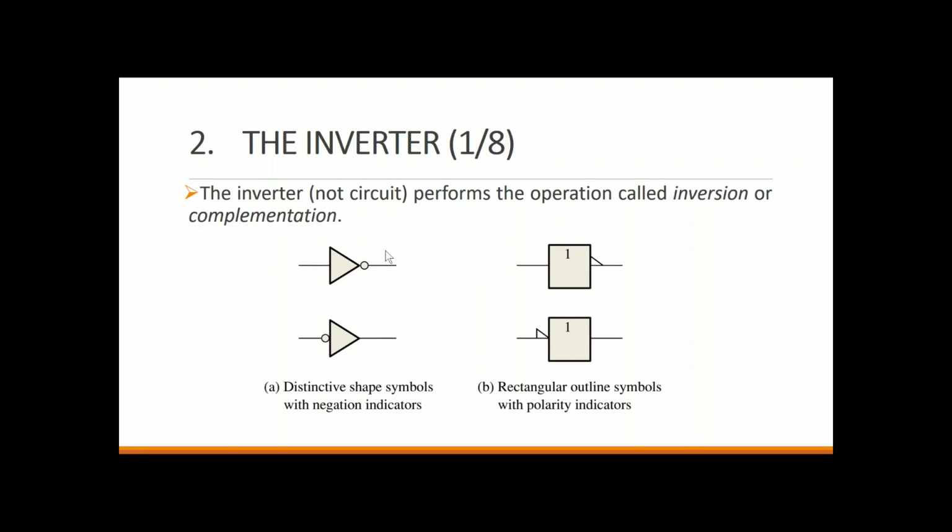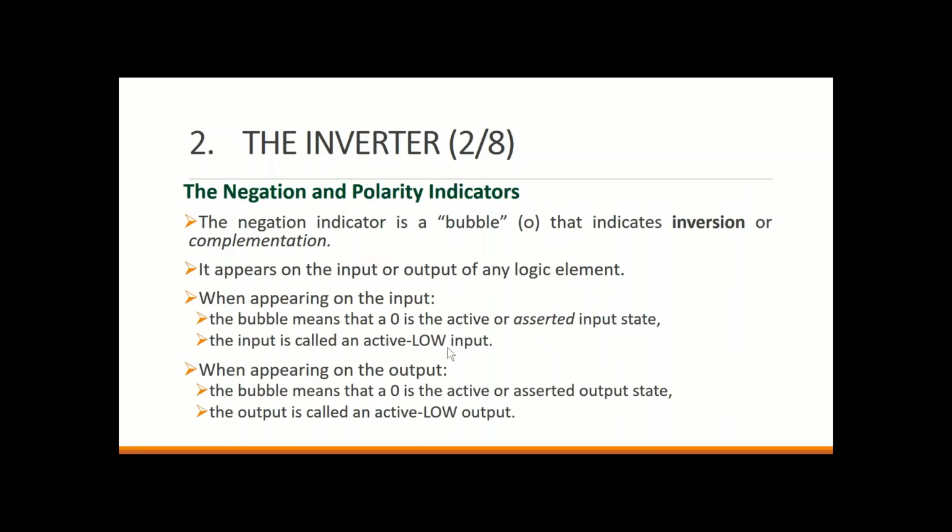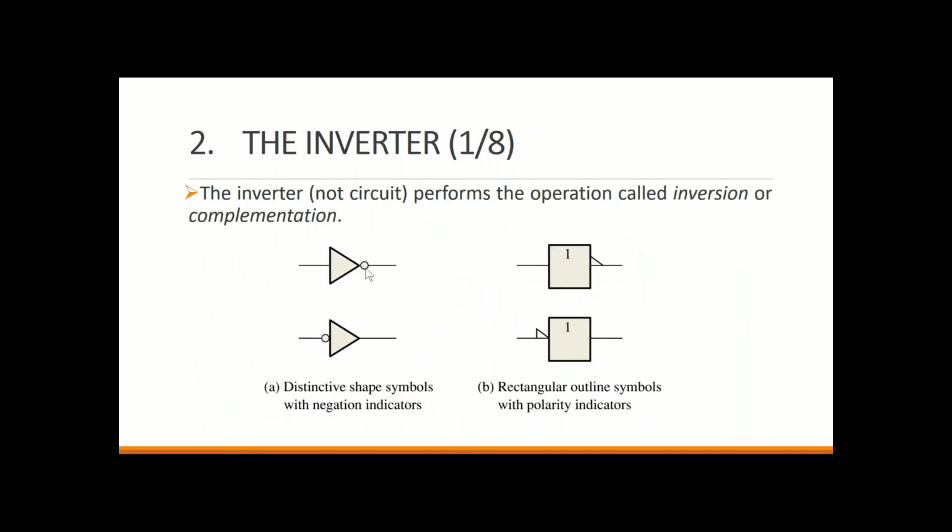That is what we refer to by active low, and this is what is written here. I just summarized it. Active low at the output produces 0, which means it should be activated in an inversion or negation process. Active low as an input means that if you provide 0, it produces 1 at the output, so the low is the state that drives the process in this case.